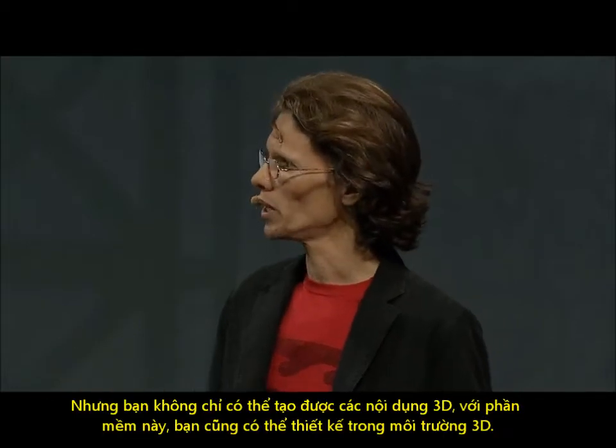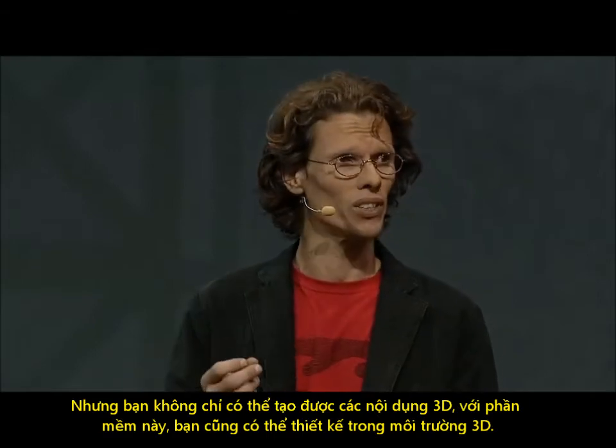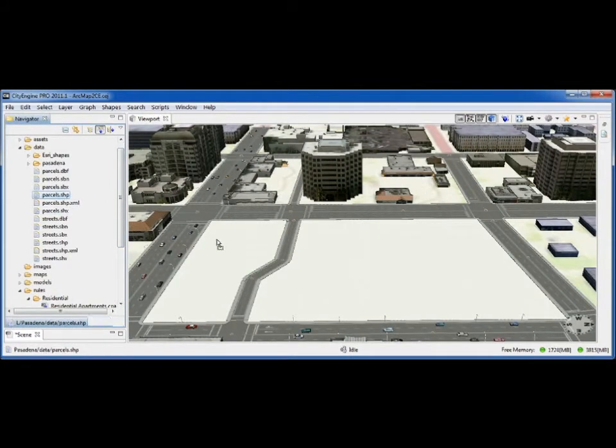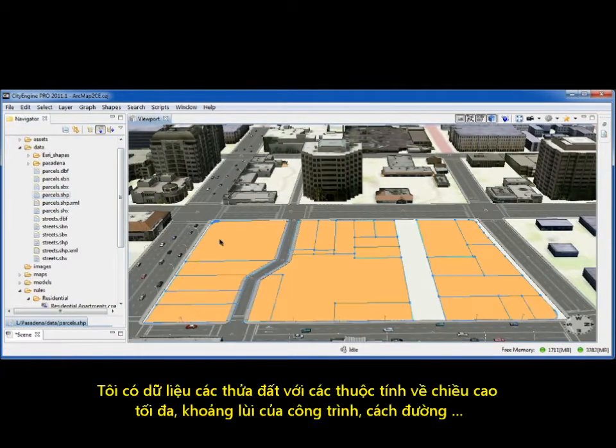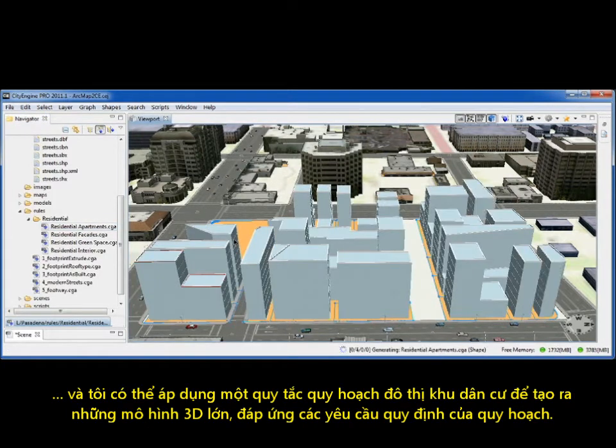But not only can we create 3D content, with this software we can design in 3D as well. Let's have a look here at this empty area in the middle of my city. I have parcel data with attributes such as maximum building height, setbacks, and offsets. I can apply a residential urban planning rule to generate 3D massing models that reflect the planning regulations.